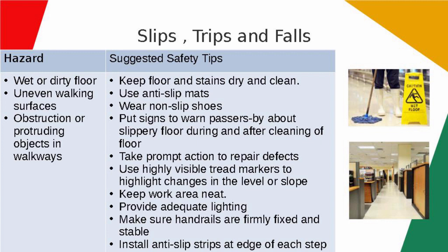Take prompt action to repair defects. Use highly visible tread markers to highlight changes in the level or slope. Keep work area neat. Provide adequate lighting. Make sure handrails are firmly fixed and stable. Install anti-slip strips at edge of each step.